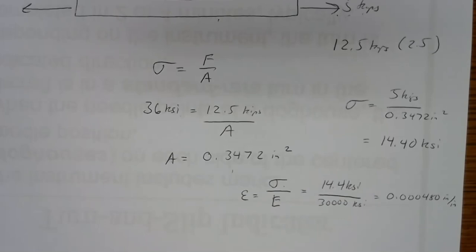Just think about what that would do to your analysis. We based the truss analysis on knowing lengths and knowing geometry. If the material moves too much and stretches out too much, then those numbers are all off, and you'd have to go back and redo the analysis with the new numbers. And a lot of times, this is what a computer program would be doing.